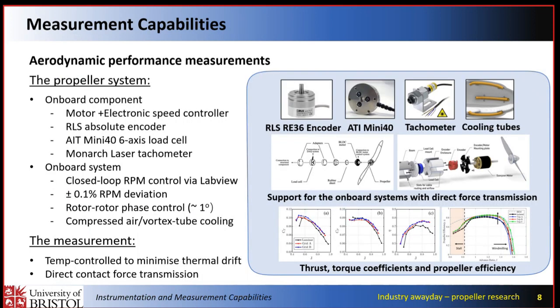And speaking about propeller, this is one of the key design or enabling type activities we do, that we need to design the propeller setup and obtain accurate aerodynamic measurements. As you have seen from Noah's or Ismail's and many others' presentations, we have quite a rich knowledge in terms of experimental design. And when we design our propeller setup, we design it as a system, meaning that we have all the onboard components in consideration, including the encoders, the motor speed controllers, the load cells, as well as the tachometer, basically to quantify the RPM.